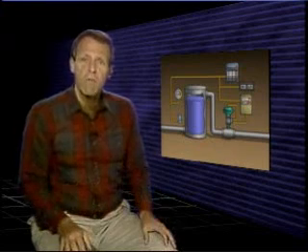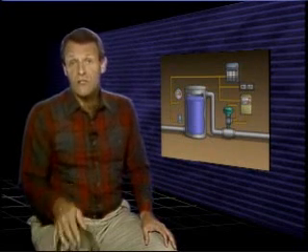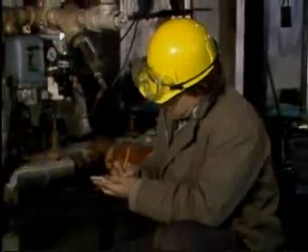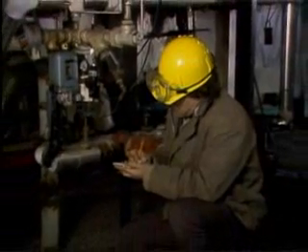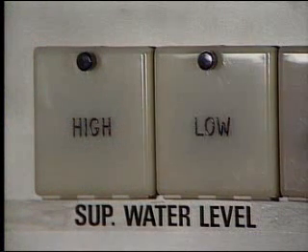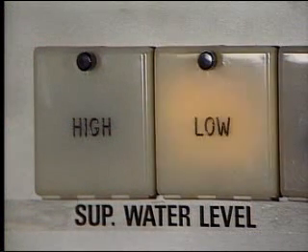An instrument system is a group of instruments and associated devices that work together to continually monitor a process variable. Some systems also control the value of the process variable. Alarms are activated when the value of the process variable being monitored reaches a point that requires operator attention. Since operators can't monitor all the different instruments associated with a process at the same time, most instrument systems contain alarms and other protective devices. Each alarm is designed to alert the operator when a process variable changes beyond an acceptable range.